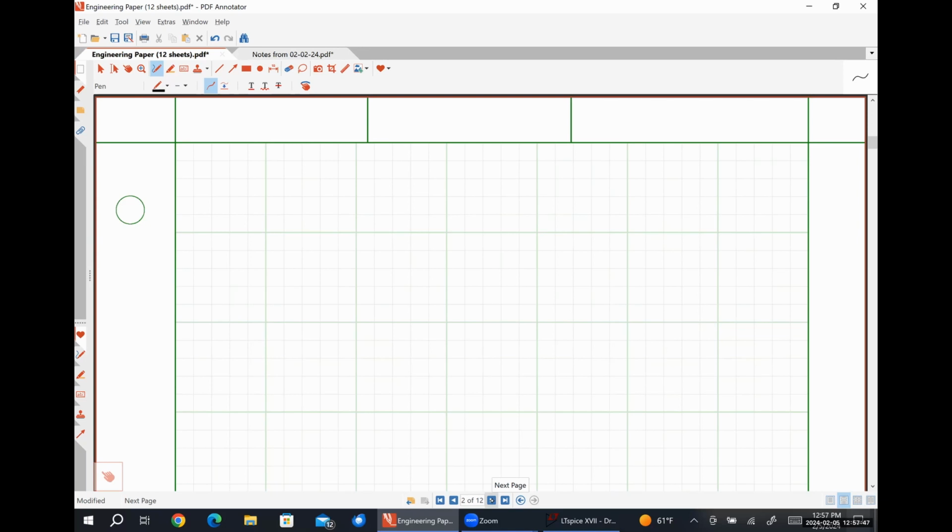So think about it from a perspective of like a sinusoidal function, okay? So let's say that we have a cosine function. 90 degrees out of phase means that we have a sine function. 180 degrees out of phase means that we have a negative cosine function. 270 degrees out of phase means we have a negative sine function, and 360 degrees out of phase brings us back around to our original cosine signal. That's it. So it's just delaying it in time by some amount that makes it look like a sine function as opposed to a cosine function. If it's a plus or minus 90 degree phase shift, and 180 degree phase shift literally just means it changed the sign.